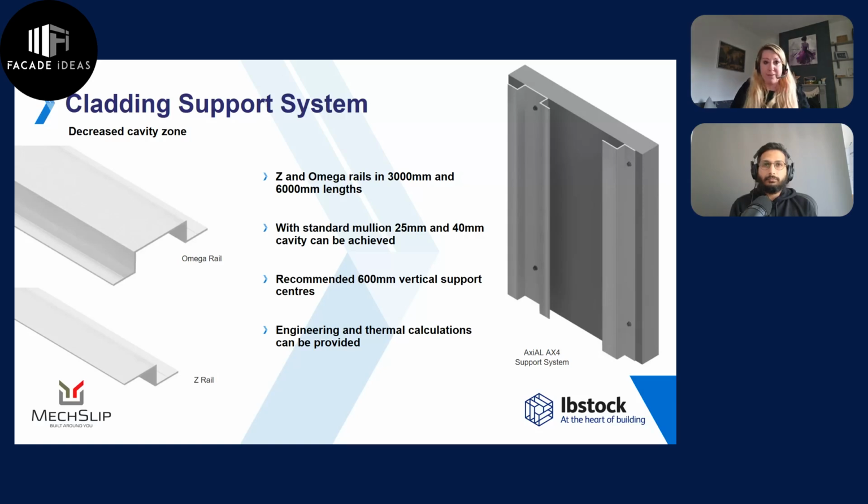Similarly, you may not need such a deep cavity. For example, where you don't need insulation, so around piers, or if you've got a brick-faced balcony across the elevation, we can decrease the cavity and omit that insulated area using these Z or Omega rails, and typically then we can affix the brick slip carrier rails directly to those.